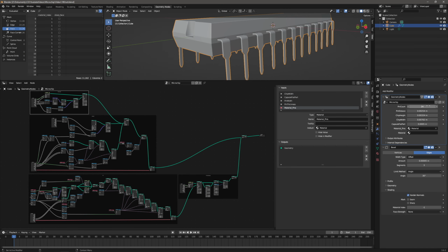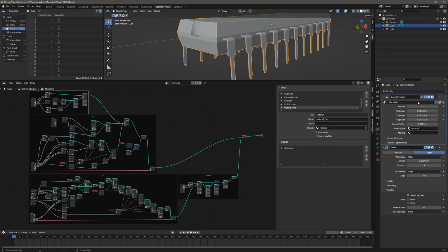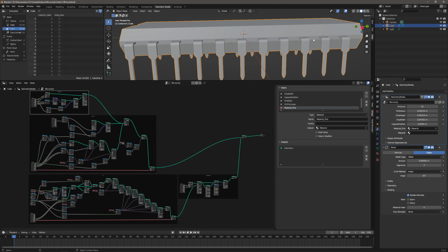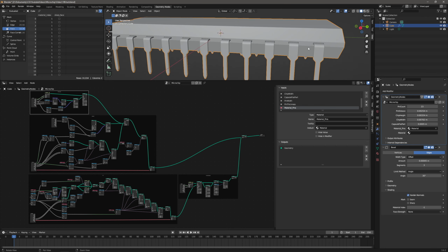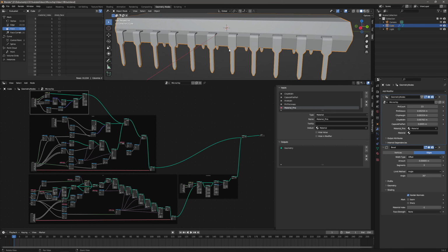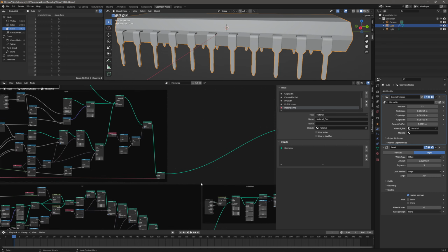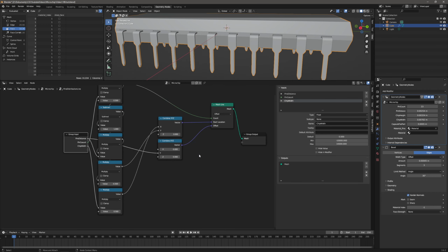One last thing I want to address here in the modifier tab is the pin count entry field. Since we can enter an odd number here, we are multiplying it by 0.5, and that will kind of mess up the alignment of the mesh line and the capsule, as we are getting a non-integer number as the result.